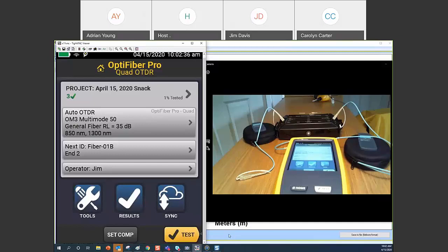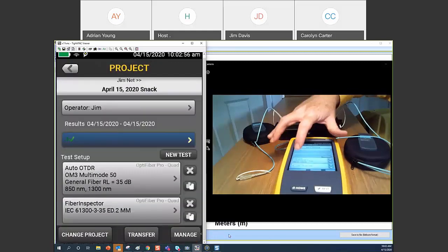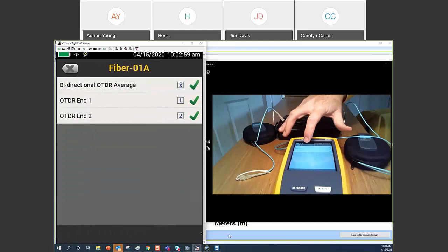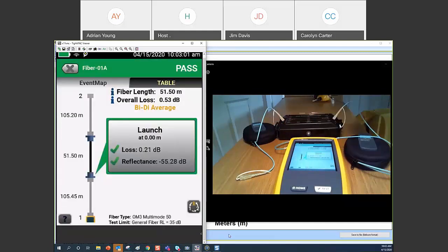Yeah, but like I said, if we look at that link in front of us, for example, and we assume that the total loss of that link is maybe half a dB, and the application requirement is 1.5, then it will work all day long. Think about this. That suggests that those connectors in there could be, say, 0.8 dB, 0.7 dB each, and that application would still work. But the specification that you're installing to is not 0.7. So really what this is about is holding the design.